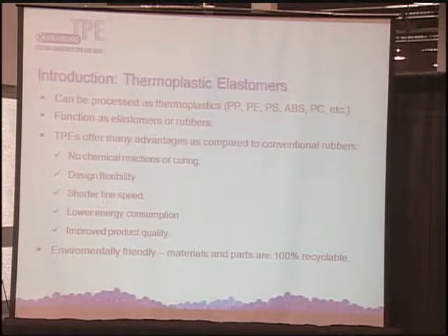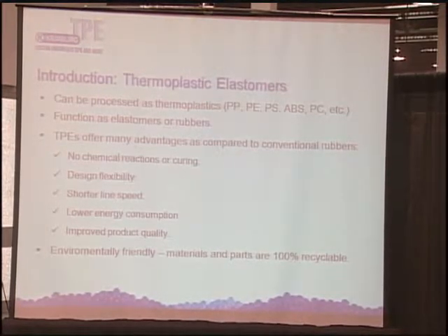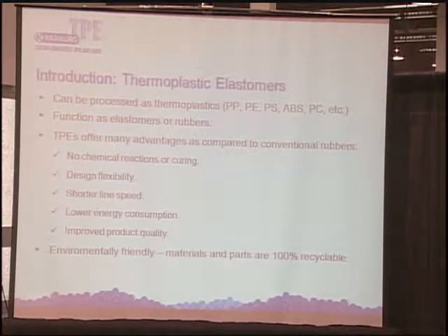And compared to conventional rubbers, TPEs have very distinct advantages, including there's no chemical reactions and there's no requirement for curing process. In other words, the materials are usually extremely pure with no chemical reaction, residues or fragments, and also offer very good design flexibility for various parts and devices.